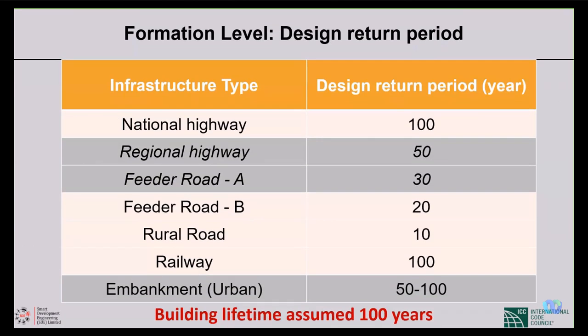Regarding the fixation of plinth level, we have to know the road level. I will come to that later. But here, you will find there are design levels for different roads and embankments. What does that mean? The top level has been raised so that the 100-year water level won't reach the top.